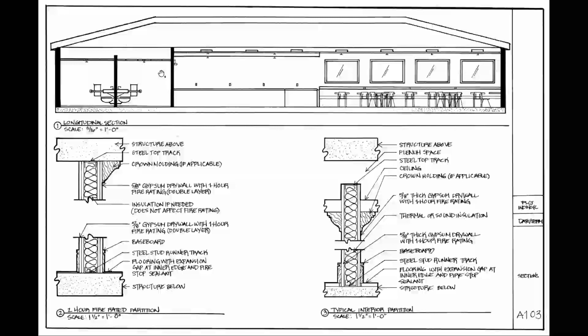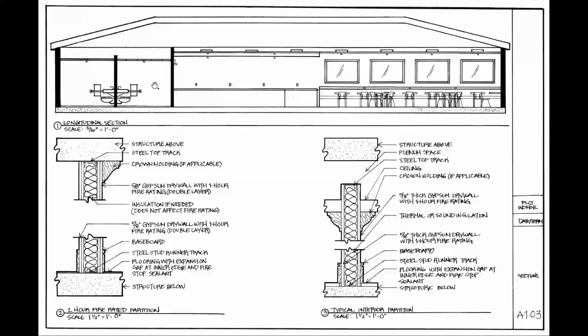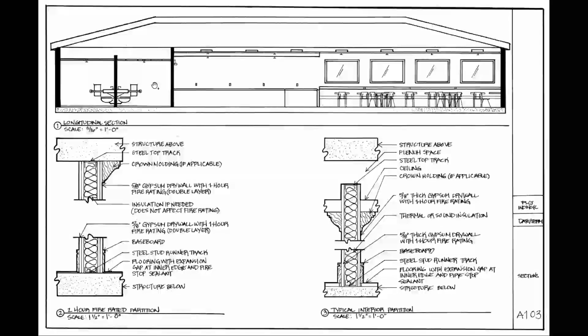So if you have a strip mall, it'll separate the nail salon from the convenience store from the place that sells grills, et cetera, et cetera. So we use it to separate tenant space, and we also use it to separate places where there could be a fire. So as I told you already, back here is the kitchen. And so if there's a fire in the kitchen, or if one of these coffee pots explodes over here, there's a separation between these two spaces. So that's the first thing that makes a partition fire rated.